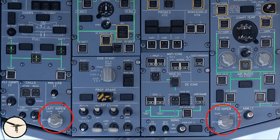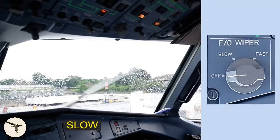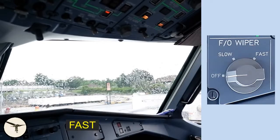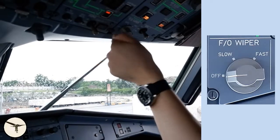The windscreen wipers are controlled with two knobs on the overhead panel, one for each pilot. The wipers have two speeds, slow and fast. When selected off, the wipers return to park position. You should consider slow to be for taxi and fast to be for flight.